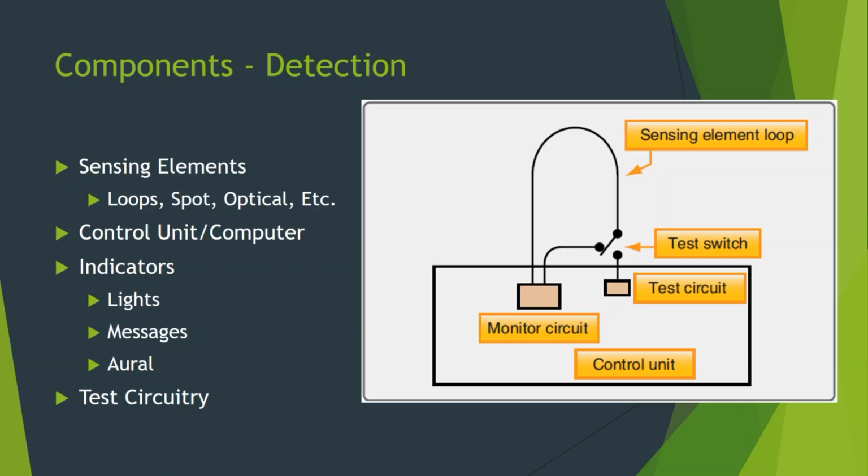On older planes, like the oldest planes I had to work on, we would actually have 2 test switches for a loop. One of them would put a ground on the center conductor of the loop, which triggers a fire warning, right? So we could show, okay, it'll trigger a fire warning. The other one sends a current, almost like an ohm meter from end to end. It says, okay, your loops don't have any breaks in them, from end to end.